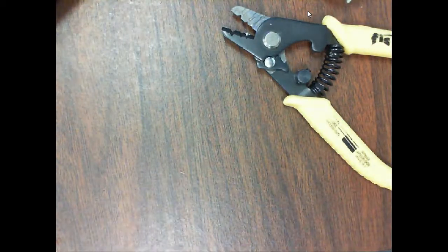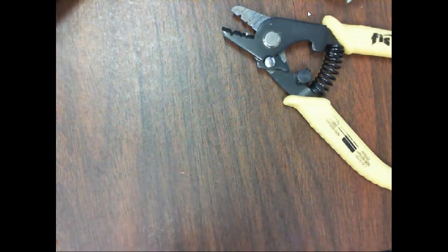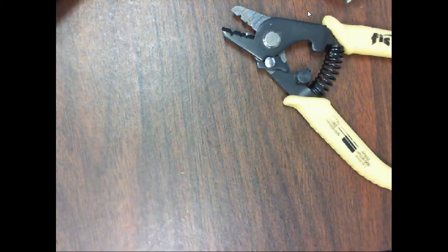That's tight buffer though. So what we mean is that inside buffer is actually in contact with the buffer coating. It's in contact with the buffer. A lot of people say it's in contact with the cladding, but they don't know. That buffer coating's on there, right? And the buffer coating is on there for what? For protection. But when you terminate it, you got to get that buffer coating off because your connectors don't handle the buffer coating. They handle the cladding.